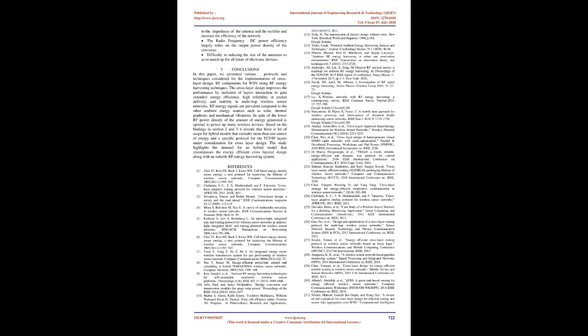proposed a harvesting circuit that is designed using a 0.18 µm CMOS power management system for a wide range of ultra-high frequency, UHF. The architecture claims to be power-aware and has adaptive DC-DC conversion ratios with PCE 59%. Safri et al., 2018.